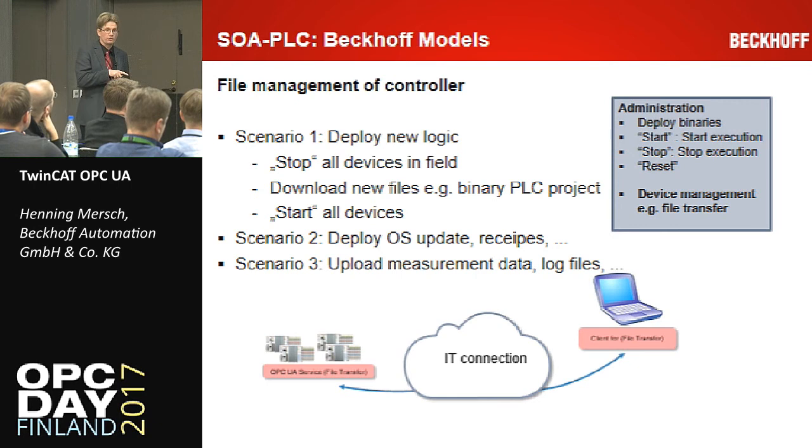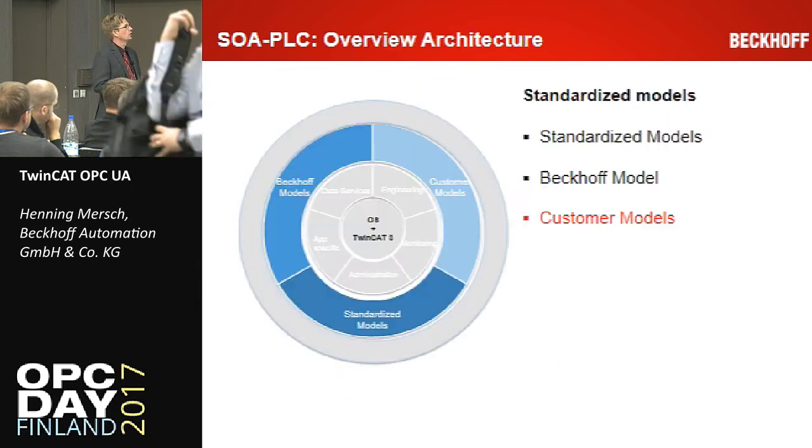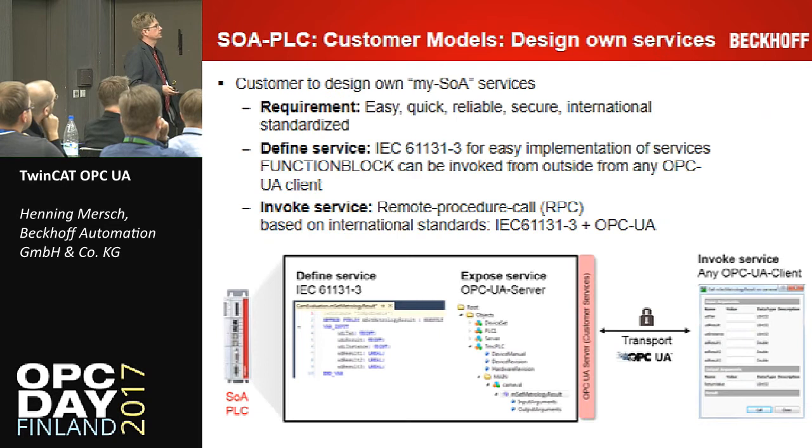But that is again Beckhoff specific. Our Beckhoff controllers have their PLC program represented as a file on the file system, so on the SD card or whatever we have. That is Beckhoff specific and not part of a companion specification, so it's not independent of it.